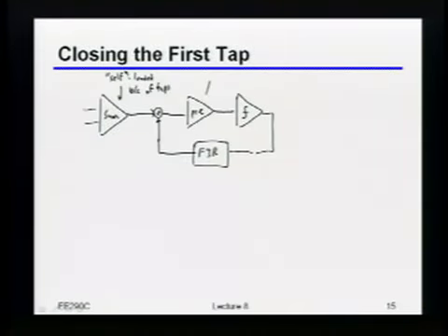Okay, so now, if I look inside of the preamp, let's say the way that we talked a lot about in 240, first of all, I try and make that thing have a pretty high bandwidth, which means that I have to spend some power because I'm worried about kickback, right? So I want a low impedance there. But at the same time, this is also a convenient place for me to do offset cancellation. Well, that means that preamp is going to be loaded by those offset canceling devices. Okay? So again, it's going to tend to be quite fast, but still has some loading that it has to deal with in terms of power and speed and so on. Okay? Well, so now if we look inside of that comparator, remember, I don't want to be dealing with huge swings.